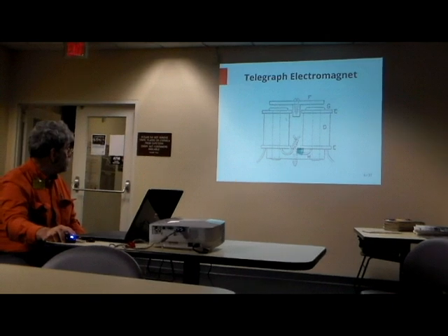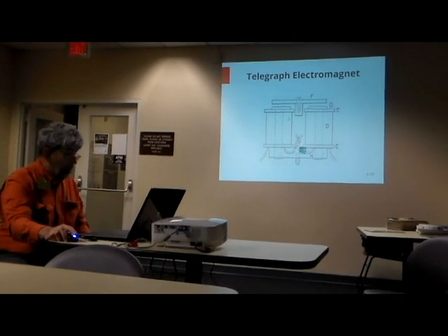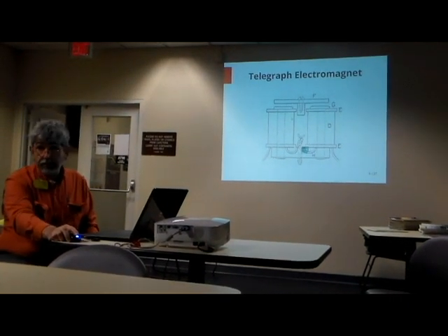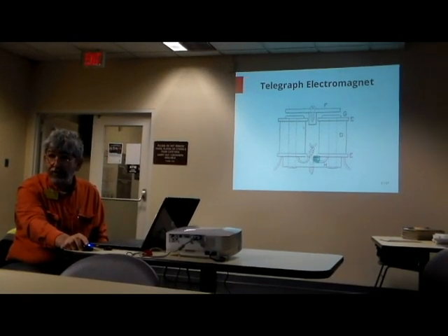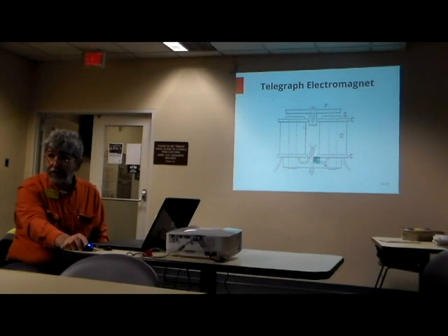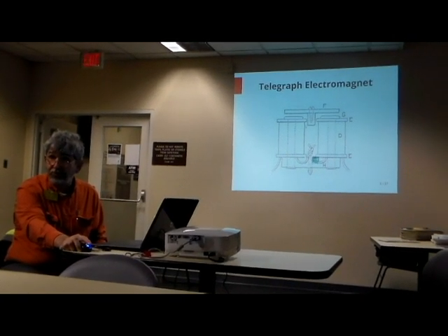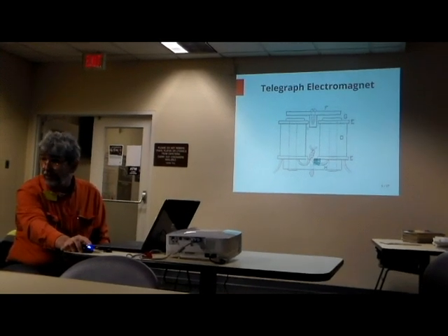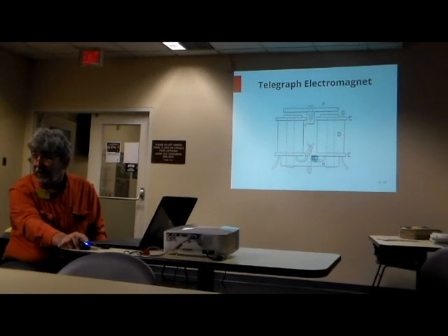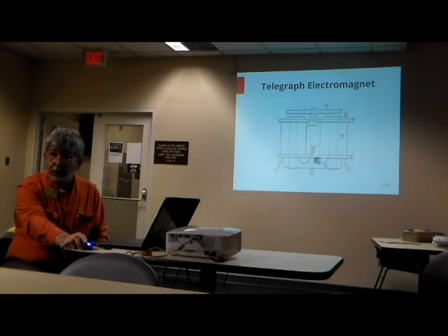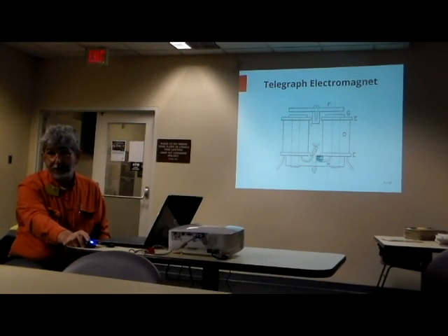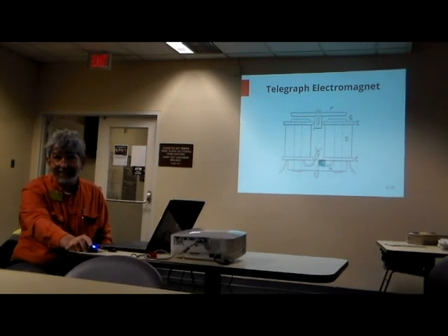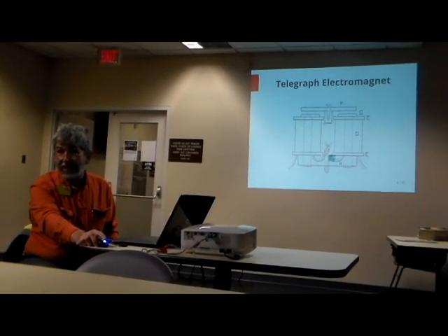Another little wrinkle I'm going to point out on this slide is that one of the sounders you're going to see pictures of is both a 400 and a 100 ohm sounder. Apply a little Ohm's law: it's 400 when the coils are in series and drops to 100 when we wire them in parallel. The only thing we have to be careful of when we rewire them in parallel is that we don't wire them so they cancel each other, because then it doesn't work at all. But that's the only caveat there.